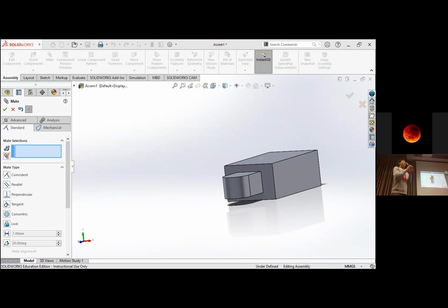So then when you have your STL file, which is composed of a bunch of triangles in 3D space, and that's only an outer surface compared to an actual solid in, let's say, a SLDPRT file, we still can't use it to print. We need to slice it into G-code, which is basically a set of instructions telling the printer where to go at what time, and how much filament to extrude per move.